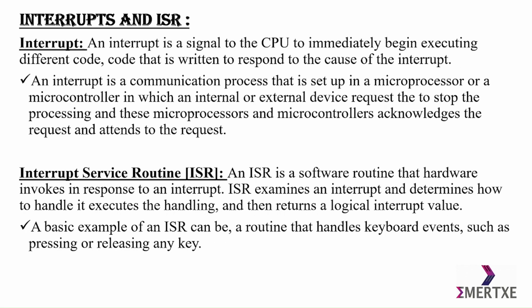ISR stands for interrupt service routine. First, know about interrupt. An interrupt is a signal to the CPU to immediately begin executing different code that is written to respond to the cause of the interrupt. An interrupt is a communication process that is set up in a microprocessor or a microcontroller in which an internal or external device requests to stop the processing, and the microprocessor or microcontroller acknowledges the request and attends to it. Now know about interrupt service routine.